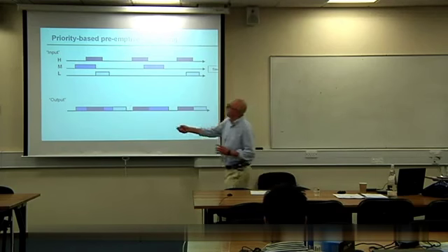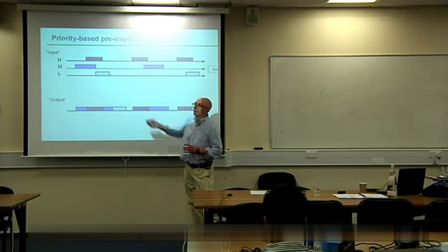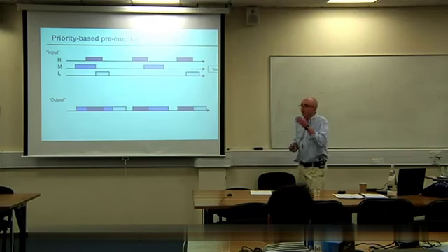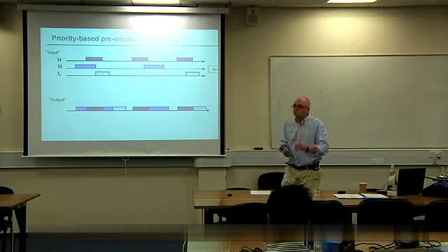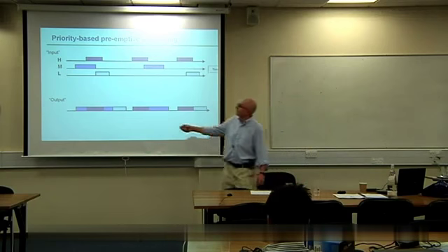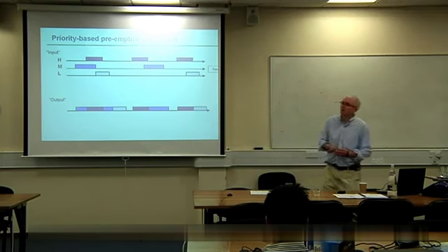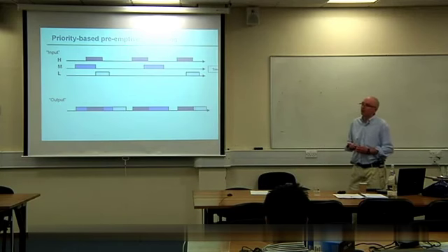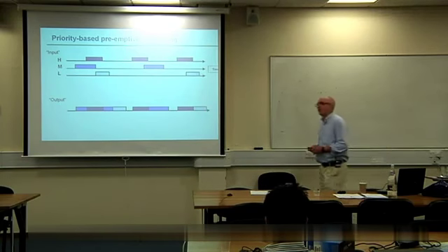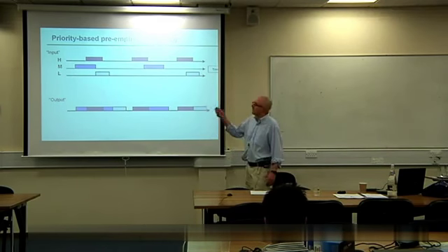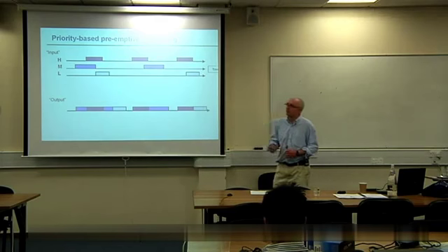Your suggestion is that this task is writing into an array and we have to let this task finish. The high priority task doesn't actually start execution at the required time. So all we can do is effectively have the high priority task wait until the writing operation on that array is complete, and then the high priority task can run. That's a challenge. And that effect is known as priority inversion.